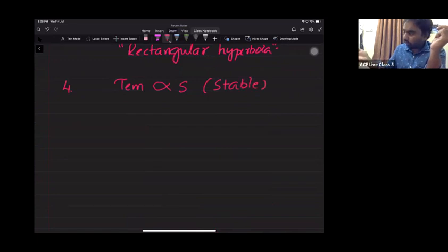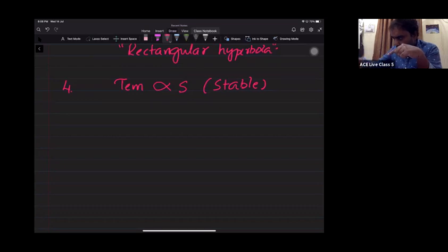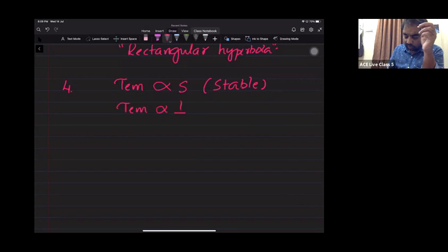With the increase in the mechanical load, the active power drawn from the source is increasing, the active power fed to the rotor is increasing, and the torque developed by the motor is increasing to supply the load torque. It is a stable operation. So with that increase, the motor torque is also increasing. But during high slip operation, the motor torque is inversely proportional to slip. It is an unstable operation.